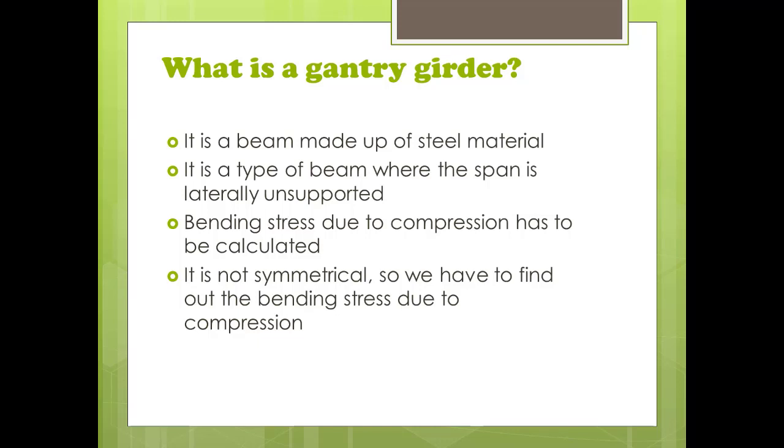When a beam is bending, there is a tendency for the top flange, which is in compression, to pull the section out of the plane, and hence it will cause buckling. In order to prevent this, it is important to restrain the compression flange by providing supports. Such beams are designated as restrained or laterally supported beams.